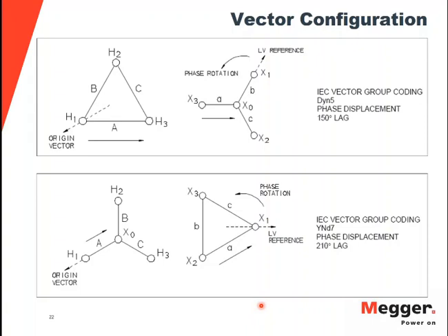Actually, if you look at the way that the test set is fixed for this test, you will do typically phase A, or whatever coil you have selected, and you go one direction with your tap changer, and then you go from the last position to the first position on the next phase, and then you go again forward or backward on the last phase. So it is better to see, and you can compare what is the response on each of the tap positions. So yes.